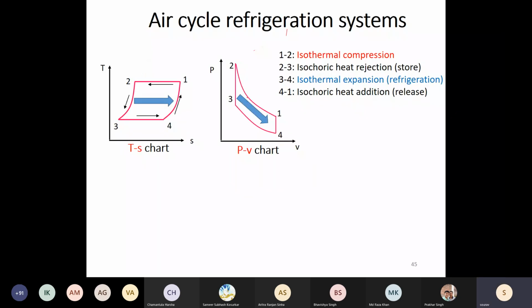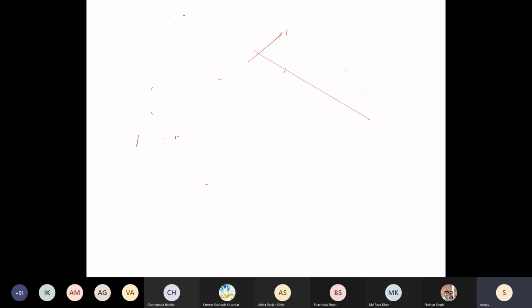So what we do in case of aircraft air conditioning is we already have the engine, and the engine is following the Brayton cycle: compression, heat addition, expansion. Again it is an open cycle, so heat rejection happens just by dumping the hot gases from the exhaust. The compressor in your jet engine is being driven by a turbine. Since our main aim is to provide thrust, we do not extract all the power in the turbine; we extract only that much which drives the compressor, and the rest provides thrust.